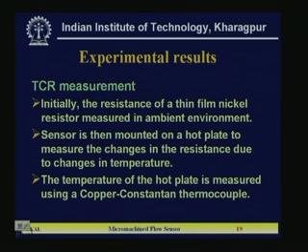So, first is temperature coefficient of resistance measurement. There, the thin film nickel resistance measurements are all done in an ambient environment at room temperature. For TCR you do not need the fluid flow. TCR means temperature coefficient of resistance, so you have to increase the temperature of that particular film and measure the resistance change. Okay. So, that is the objective.